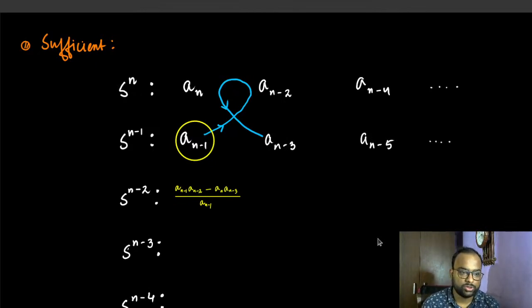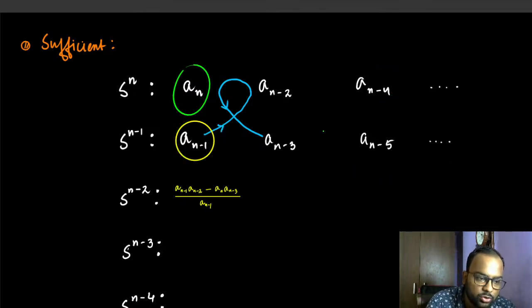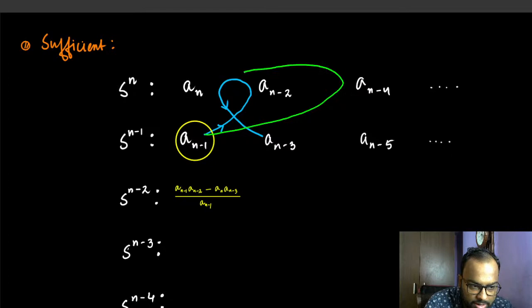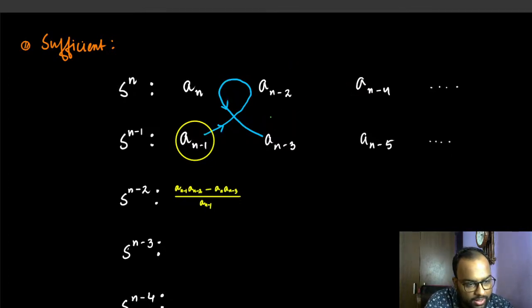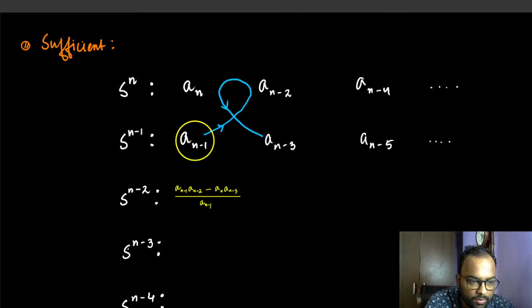Okay, first term in the next one. So we actually construct the first two rows using the coefficients of the polynomial, and then we construct the next rows using this terminology. So this is the pivot term here. Then the next one would be like this. We start from here, we take the determinant of this and this, and put a negative sign, which means we can do this calculation in a very simple fashion if we remember this structure. It is a very similar structure. So we start from here once again, multiplying these two, and then subtracting the product of these two.